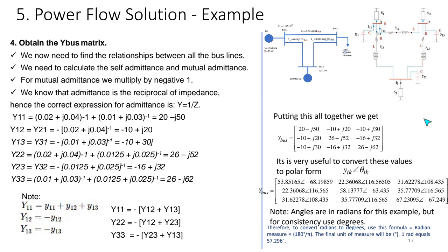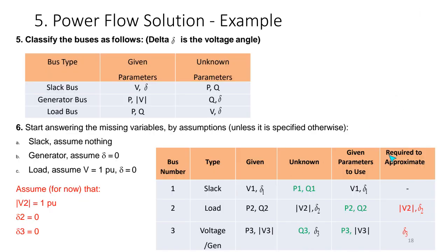All right. So the first step of the Newton-Raphson load flow method is taking the given power system network, formulating the Y-bus, and writing the Y-bus matrix in polar form. That is the first step. Any questions from the Y-bus formation? If not, I move on.